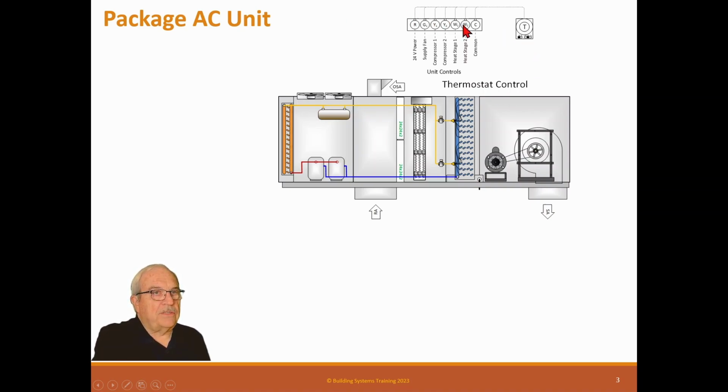But it also has these lugs, and these lugs basically are for a thermostat to be able to run this unit, or a DDC controller we can put on that. And this is very similar to a residential one that has a power wire. That's the power coming up from the unit. And 24 volts goes over to the unit thermostat, and the thermostat has different controls in it.